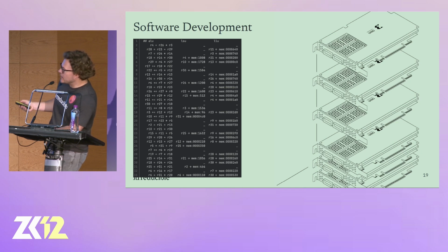This assembly here shows you the ALU, load pipeline, and store pipeline, and how they look in the time domain. You will see very interesting things: you read from memory and store to memory in the same clock cycle because we are featuring true dual port memories. We actually support this case efficiently. And if you look at the computation side, you will see a lot of multiplications and additions back to back. So this is really the output of the compiler, which was written symbolically, and these are the instructions that get executed on this multi-core CPU.